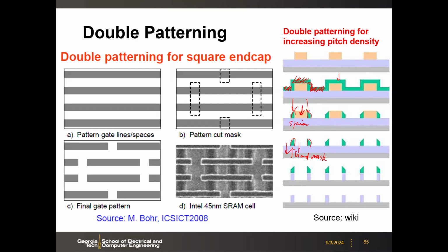If this purple one is silicon, then after you use this as a hard mask, you etch the silicon. Then what you have left over here will be a piece of silicon fin. This is a FinFET. So the green is with photolithography, and then everything else is just chemically etched.